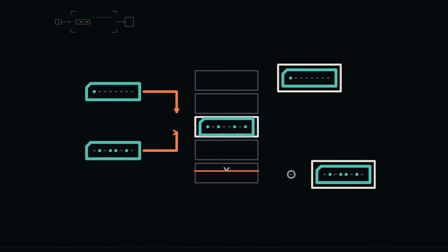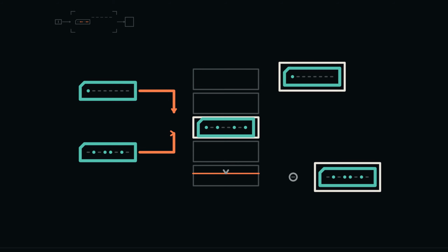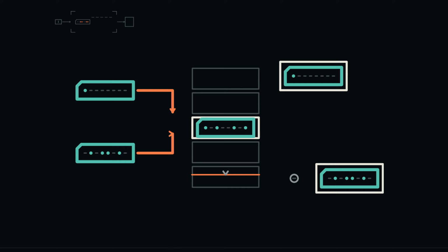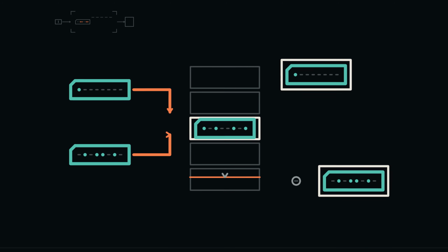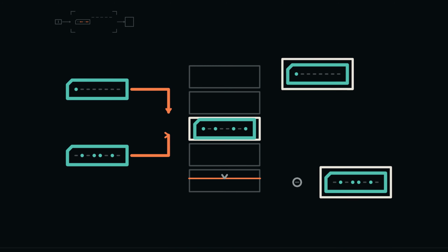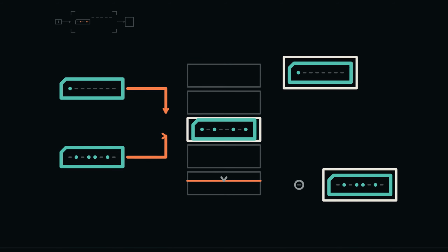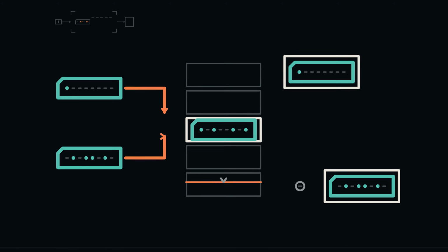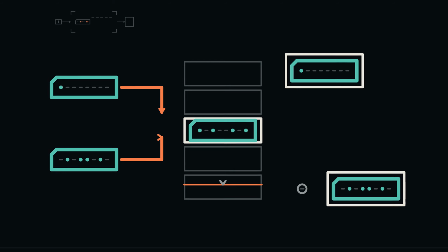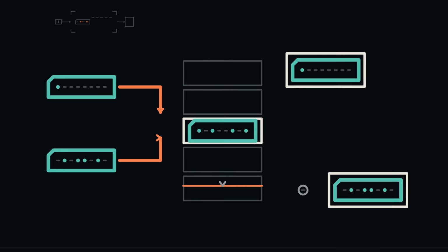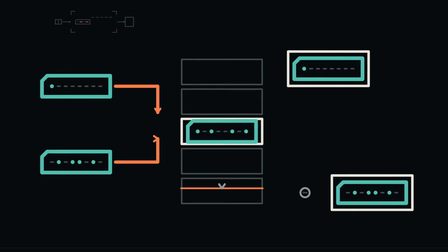Second, R2 drives its byte hexadecimal 5A onto the bus, and MDR is selected to receive. Predict the ledger at the next edge. MAR remains 80, R2 remains 5A, MDR becomes 5A. Memory at 80 still remains A5 because capturing the write data and committing the memory write are distinct controller actions. MDR provides a stable staging place between the shared bus and memory. It is not a second copy with independent meaning. It is the controller visible register currently preserving the byte intended for the transaction.